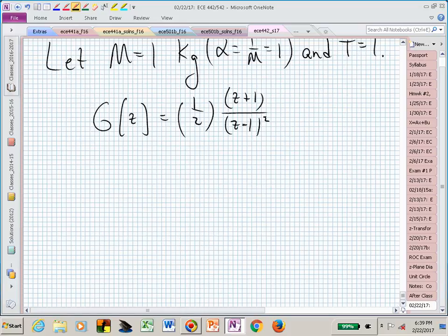And I think you're just dying to see that in the z-plane. Are you not? You just want to see poles and zeros. Because you're used to seeing, what's a double integrator in the s-plane? 1 over s squared. What would that look like? 2 poles at the origin. Now what do we have?